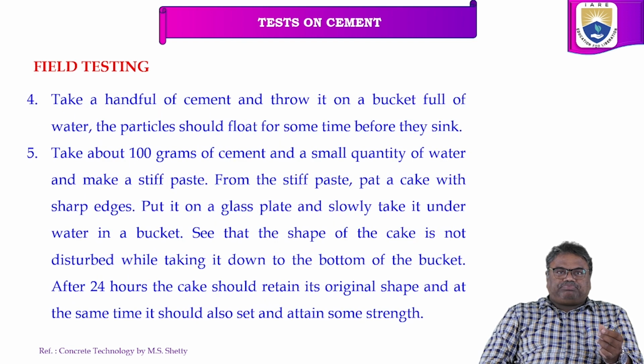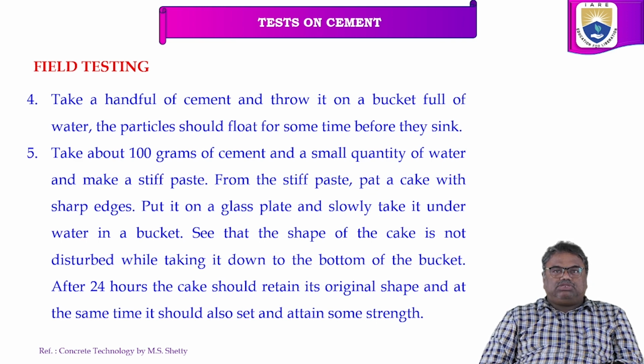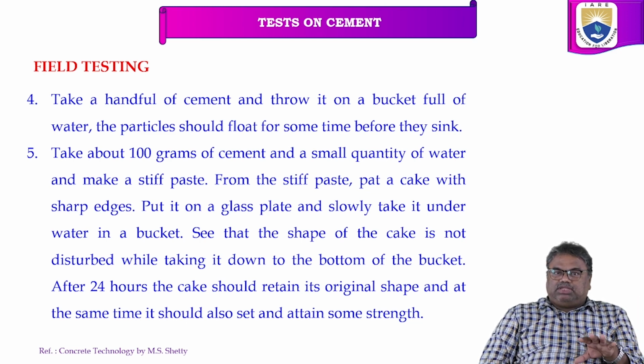The fourth one: take a handful of cement and throw it in a bucket full of water. The cement particles should float on the water for some time before they sink. To float is very, very important.